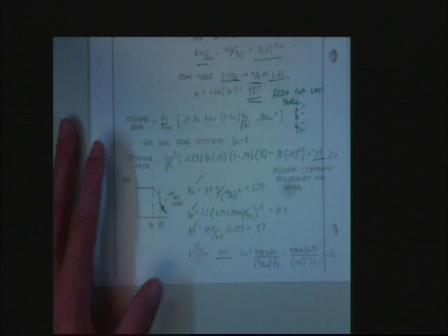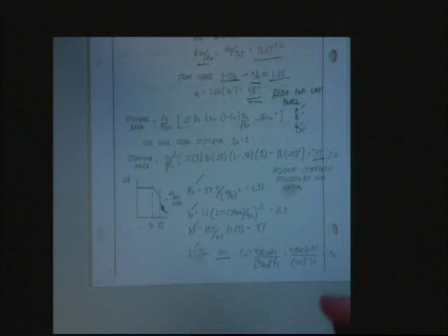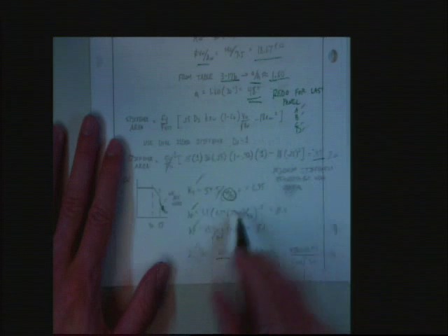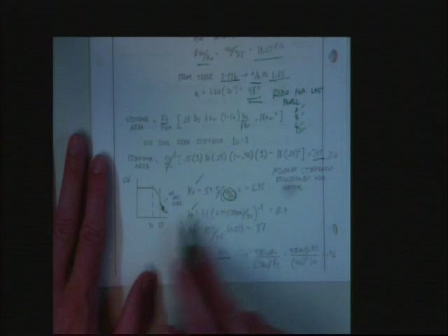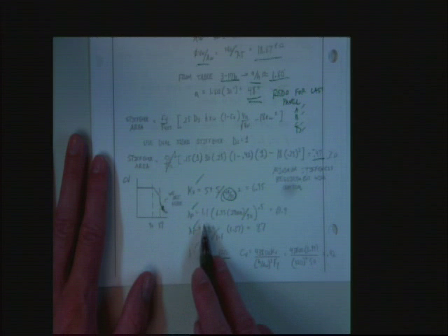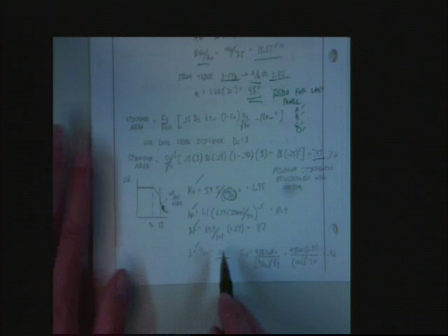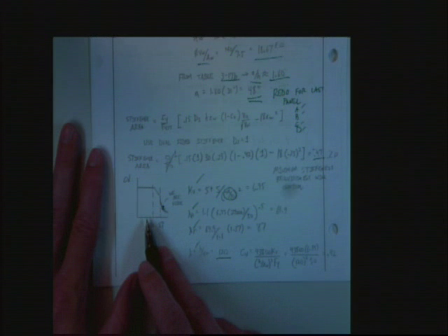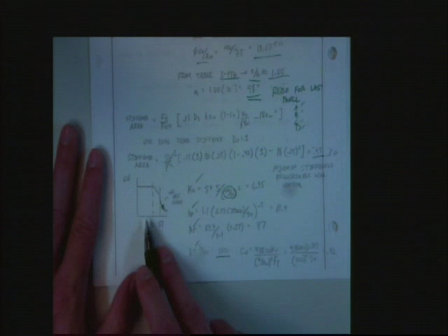Now notice, one thing that's a little insane about this is that you need to know your A over H to find your K sub V. And you need your K sub V to find your gamma sub P. And I think gamma sub R as well. So you don't even know what this diagram looks like until you've already chosen what your stiffener spacing is. Does that make sense? I wish it wasn't that way, but that's what it is.